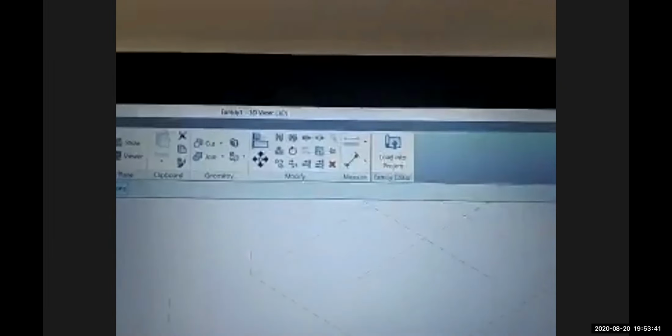Show me the bar once again closely. I want to see what is happening, whether you have folded the bar or something. Should I activate dimensions by any chance? No, that is fine. I think you're doing something wrong. When you don't select the rectangle, you haven't created the rectangle properly. Maybe that might be the reason the create form option is not coming.